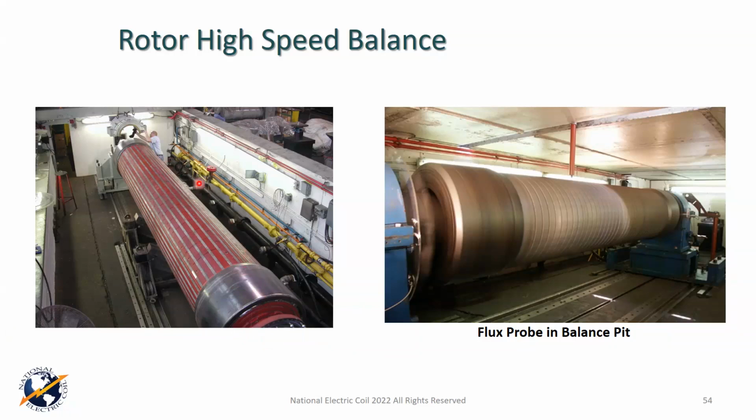And most repair houses and many of the OEMs on rewound machines, their insurance policies and their internal policies say, look, we're only going to 110%. We're not going to 120. So just keep that in mind. But going back to the process, once you get up to 10% over on 3,600 RPM, that'd be 3,960, you hold it for a minute, you come back down.